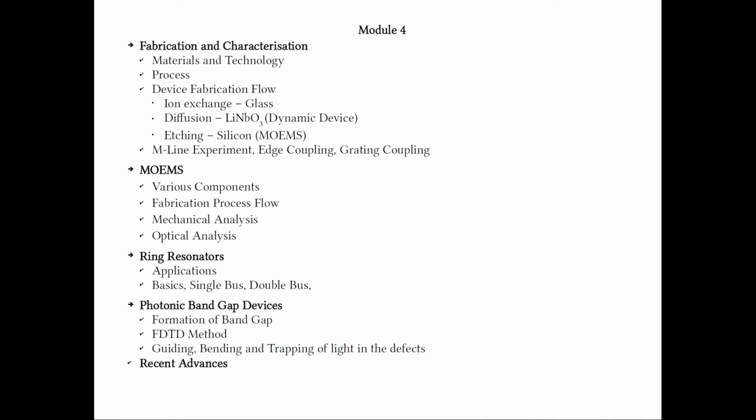And also on silicon, one of the most common techniques is the lithographic patterning of the silicon layer by using etching, and it is also possible to combine these optical waveguides with MEMS structures to create many other important properties.